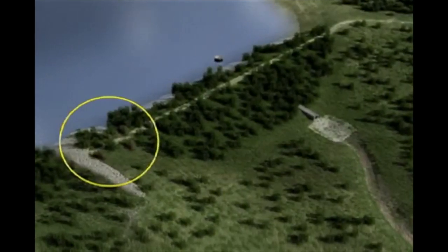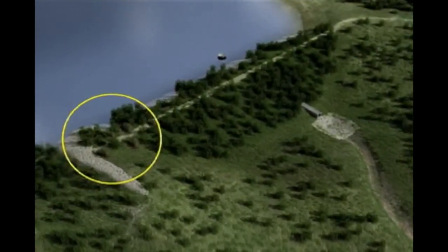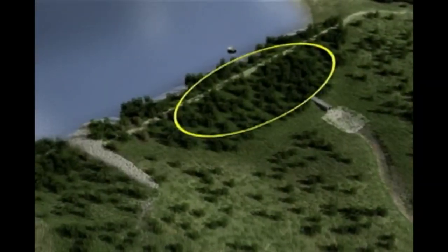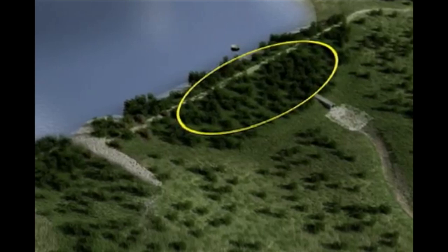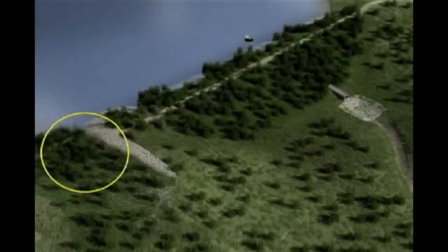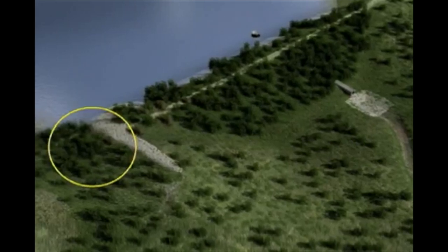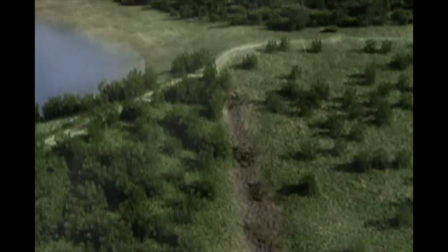Trees can become uprooted, damaging the crest or slope of the embankment. Heavy vegetation will make inspection difficult and provide a haven for burrowing animals. Trees and brush can block spillways, reducing the dam's ability to pass large flood flows. Erosion of embankment surfaces is undesirable. Rainfall runoff can create erosion gullies, particularly where the dam meets up with the abutment.